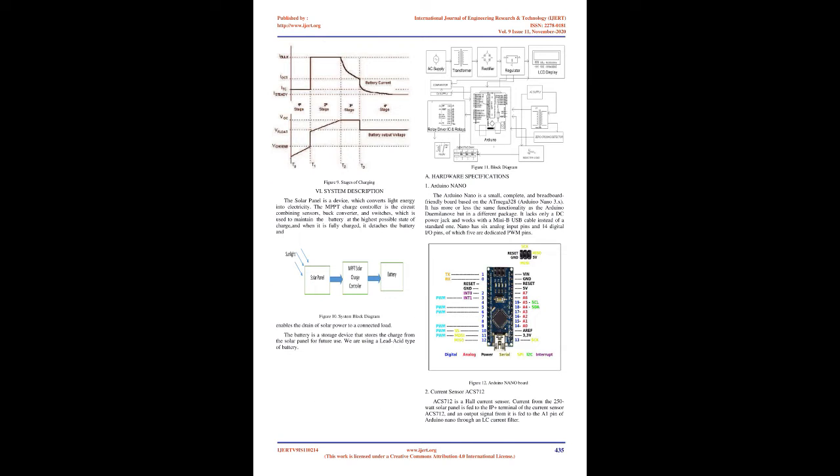It is known from the above that the constant voltage and constant current charging methods have their own advantages and disadvantages. In order to improve the shortcomings of the two methods, a constant current/constant voltage charging method is proposed. This charging method can significantly reduce the charging time, and it also has the function of self-regulating current with the constant voltage charging method and does not cause the battery to overcharge.